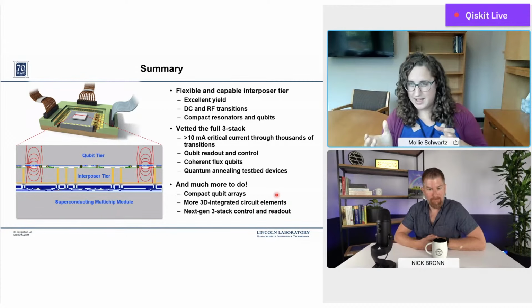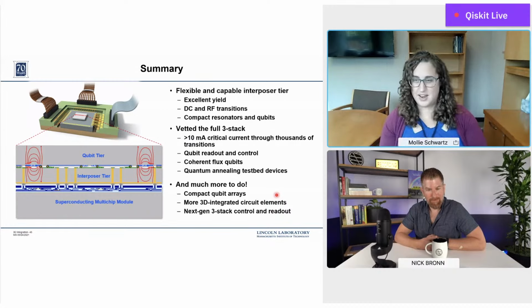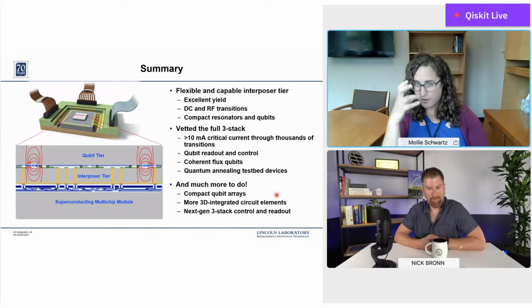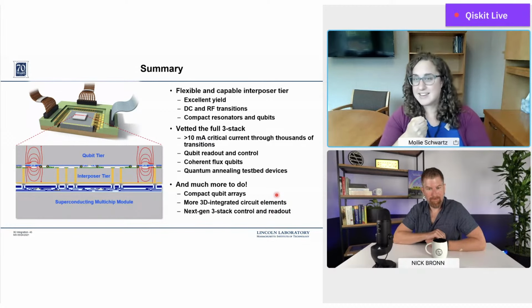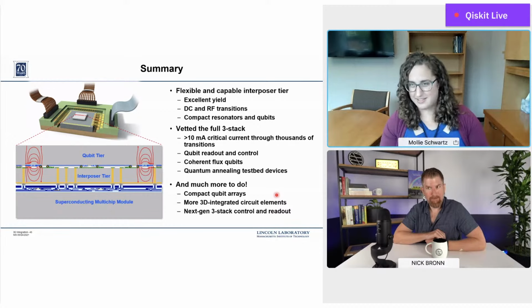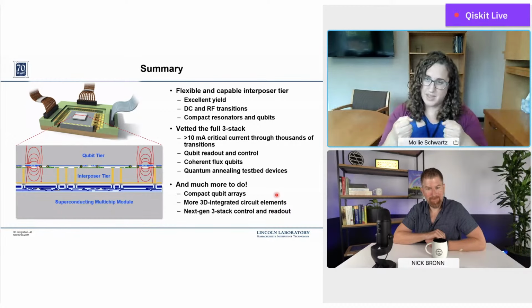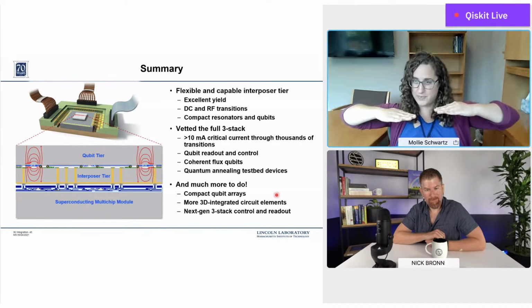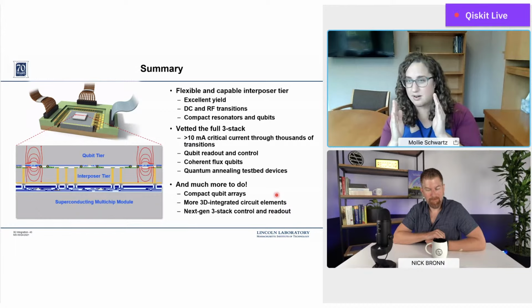So we measured a set of those, and then we measured a set of resonators that had the TSV in it, and the resonance frequency of the device dropped by like a gigahertz, which tells us that there's a huge participation of the electric field in the capacitance of the TSV itself. So the TSV is really good at pulling electric field into itself, into the silicon, which then increases the capacitance. And if you have two of them next to each other, then you get the capacitive coupling between them. That's essentially a parallel plate capacitance, which is much higher capacitance than capacitances that are side by side. So it's parallel plate, it's running through the silicon rather than through vacuum, so you get very high capacitances.